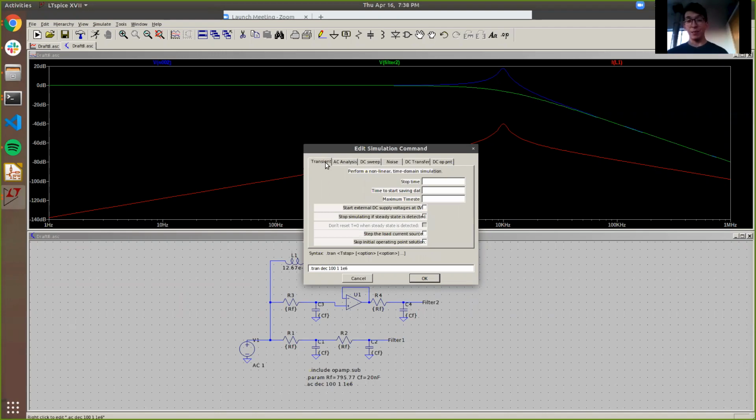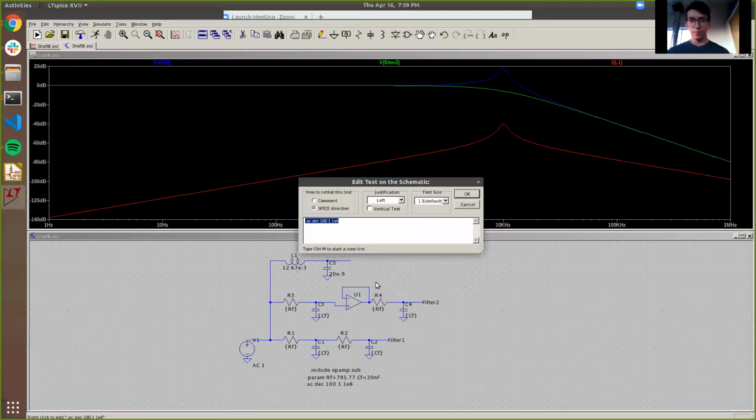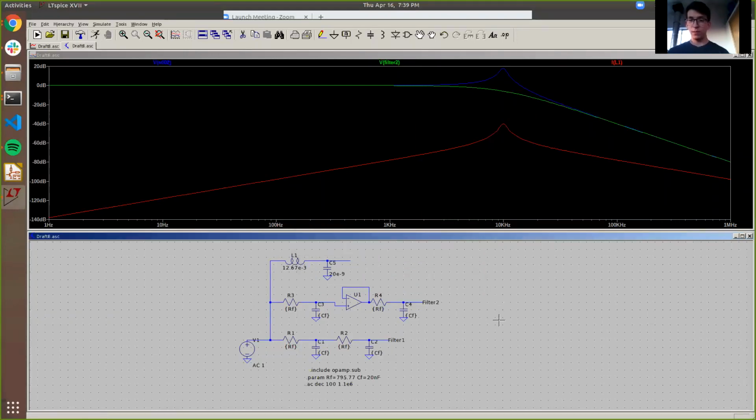You could do a transient simulation, which means you can imagine what a circuit looks like over time, between 0 and 10 seconds, for example. Then you can look at the current and the voltage of your entire circuit between 0 and 10 seconds of whatever you decided to simulate. So yes, in other types of simulation you can, but it makes less sense for this Bode plot to look at current. Did that answer your question? Yeah, thanks. Cool. Any other questions?